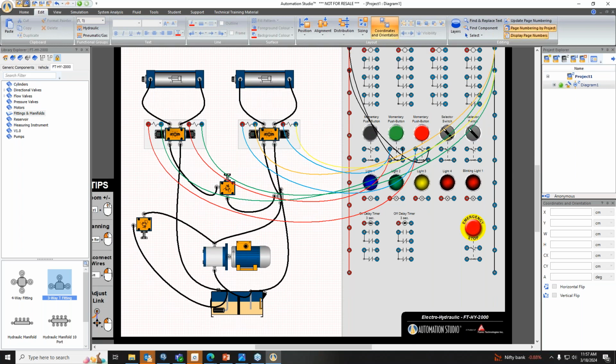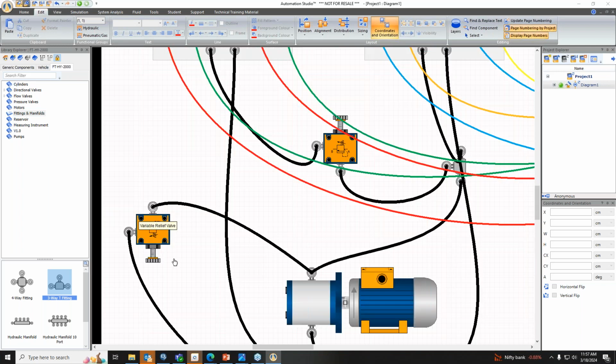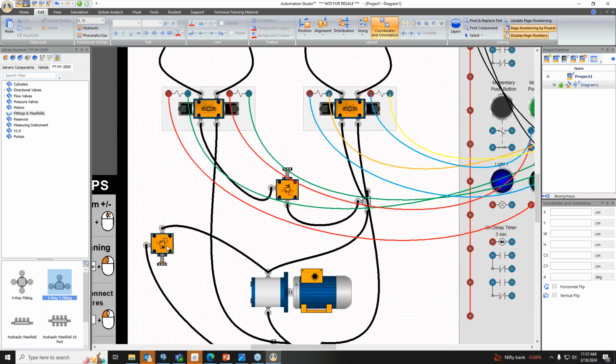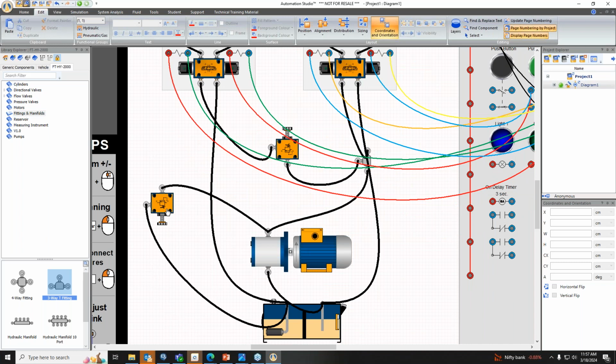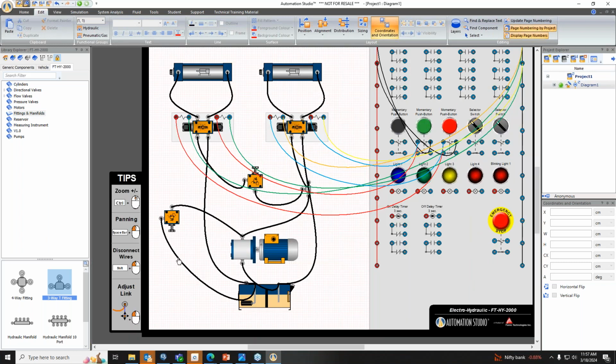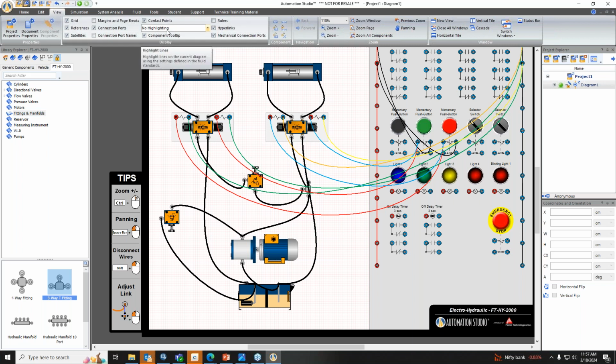And again, you can see all these lines, you can change the line type or line function from here. So you can see from the tank, from the pressure relief valve to the tank, this is a return line. So here, if you select the line, as I said, you can have different options available. Now here, maybe I can select this is the return line, and now if I go into this view, here we have the option of cross view highlighting.